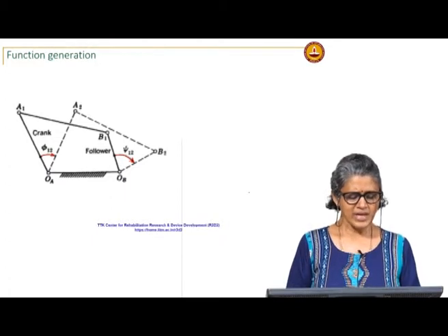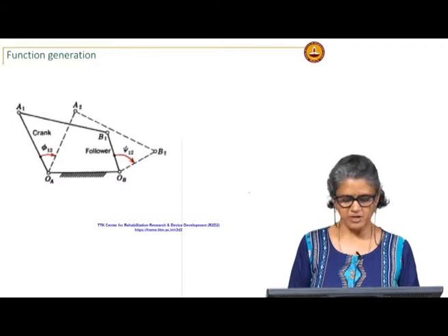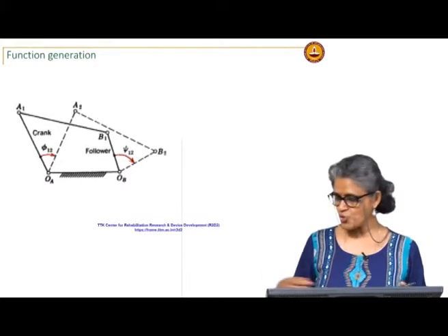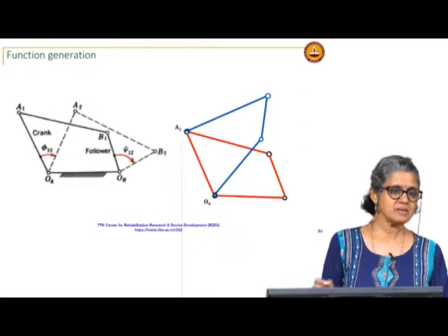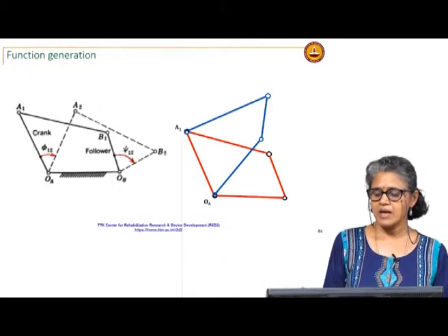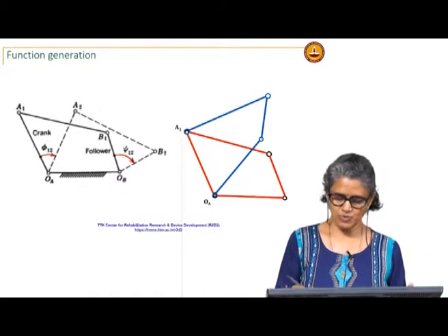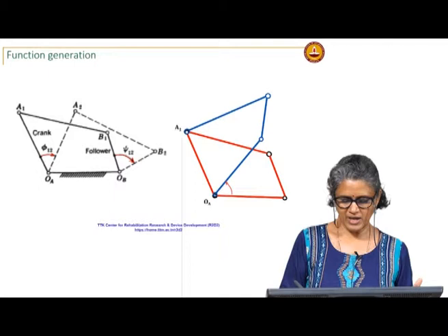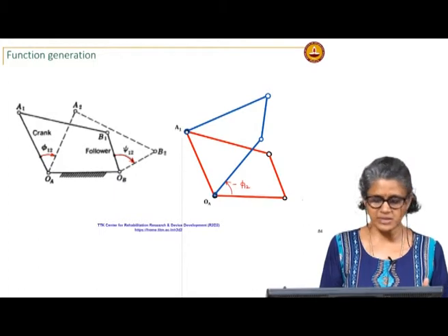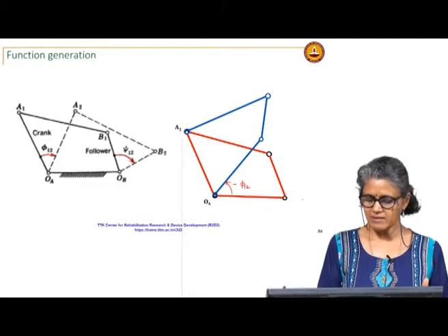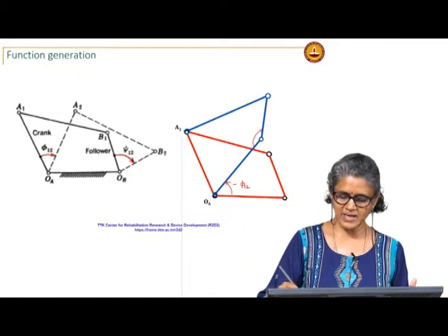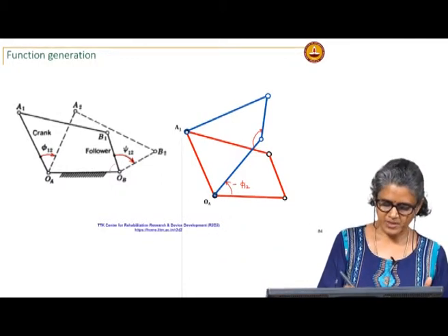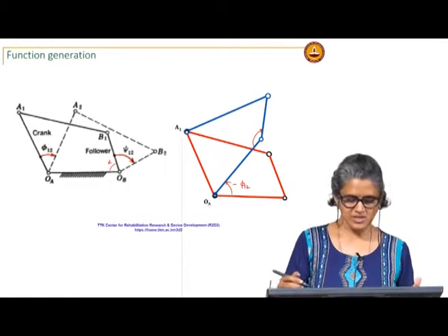Okay. So, again we will use the principle of inversion by saying, instead of OA OB being my fixed link, I will sit on maybe the input link, and then my relative motion would be that the frame would have moved by an angle phi 1 2 with respect to me. Let us just call this angle alpha.